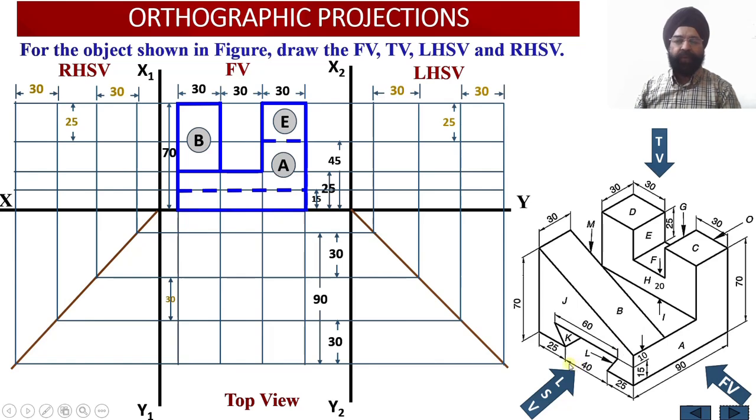is equal to 60 millimeter, while the base dimension is equal to 40 millimeter. So since this dimension is 40 and this dimension is 60, you have to move back by 10 millimeter on this side and move forward 10 millimeter by this side, so that these 2 top corners of the slot can be obtained. So what we are going to do, if this distance happens to be 25 millimeter, the distance of the top portion of this angular slot will be 15 millimeter from the rear face.